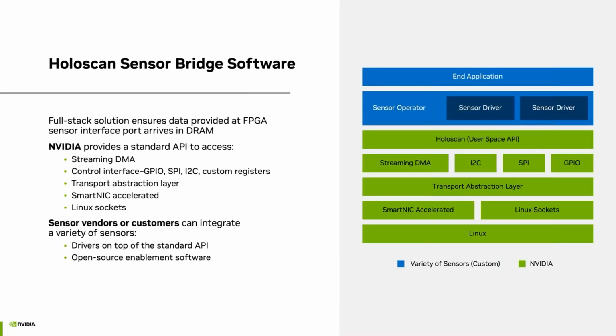Jumping into a little bit of details for the Holoscan Sensor Bridge software now. The thing that's great about the Sensor Bridge is that from the sensor's perspective, you don't need to write kernel space drivers to support all these various different sensors. It's going to be completely user space. This full stack solution really ensures that the data provided at the FPGA sensor interface can easily stream over to our compute. So with our NVIDIA IGX platform, you can leverage streaming DMA via the ConnectX, and on the Jetson, we support CPU emulation that still leverages the low latency aspects of the sensor bridge.